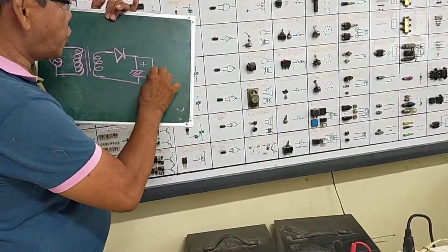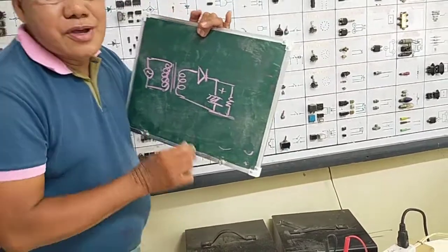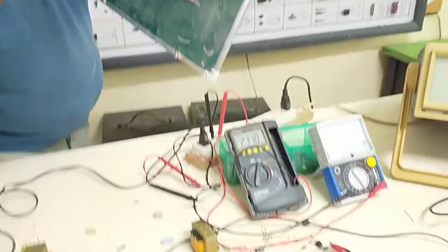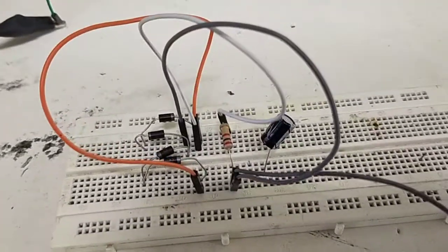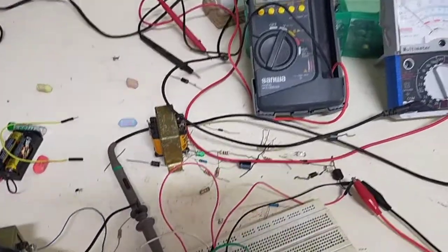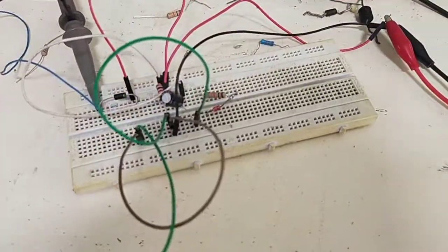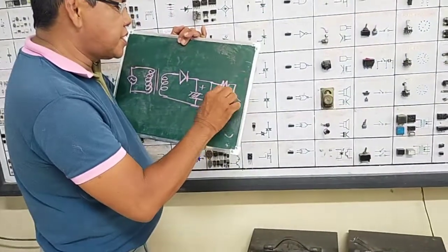We have here a resistor with a resistance of 2.7 kilo ohms because the colors are red, violet, red, gold as a tolerance. Then the Zener diode is connected here. There is a resistor and a Zener diode.